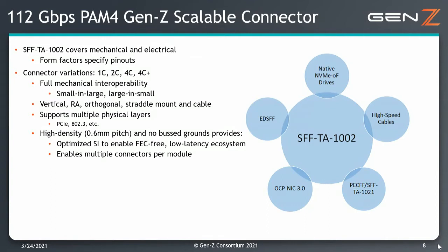The GenZ Consortium worked together to create a new interconnect specification, which eventually was handed over to SNIA, and is now defined by the protocol SFF TA1002. This standard that GenZ developed covers mechanical and electrical performance of the interconnect, while the various form factors that utilize the SFF TA1002 interface specify the pinouts. So, the versatility of the GenZ scalable connector, as well as the performance, has made it an attractive solution for a number of applications, whether that's OCP NICs, high-speed cabling, native NVMe drives, EDSFF for storage, which we'll talk about later in this presentation, as well as PECFF.